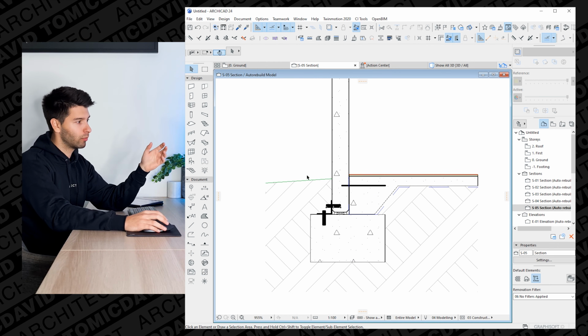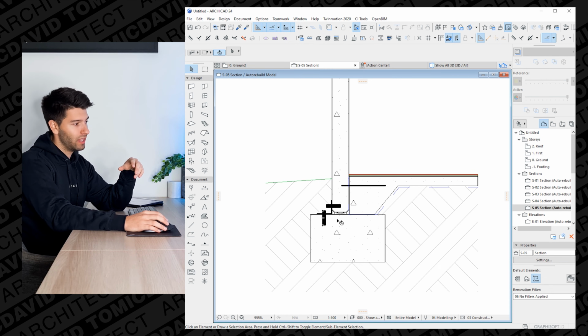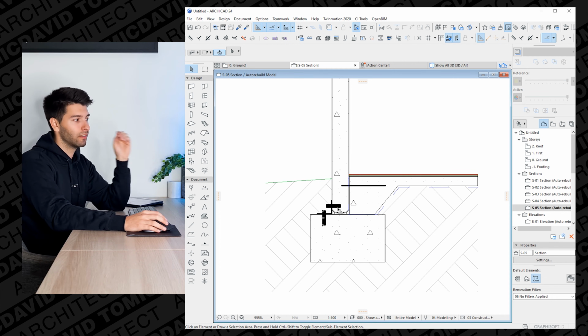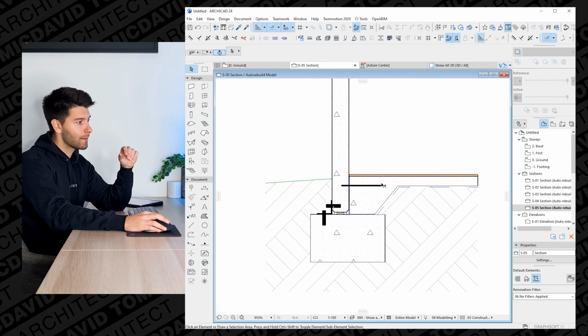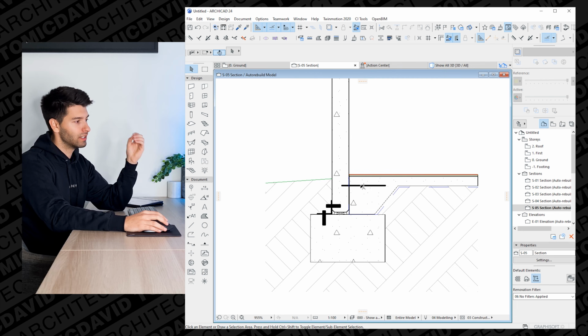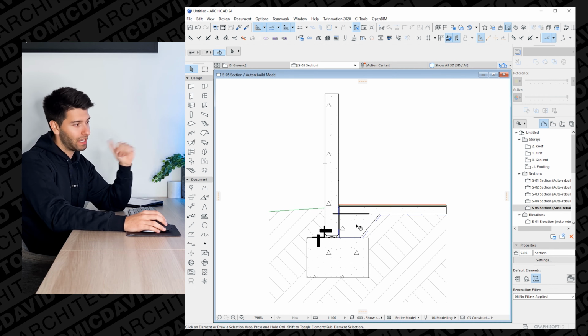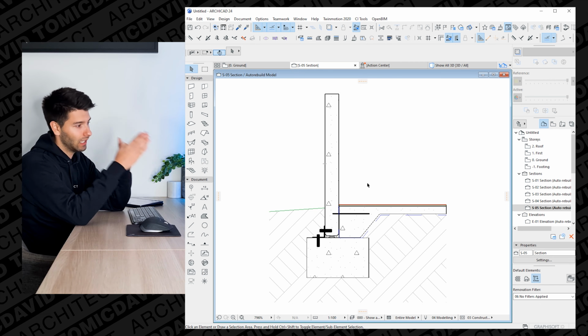So speaking from a construction point of view, that section of earth there would actually be backfilled after these bolts here had been installed into the footing and into the concrete wall. This rod could be a number of different ways depending on the construction of itself, but overall speaking, that is the tilt-up wall, that is the slab, and that is the detail completed.